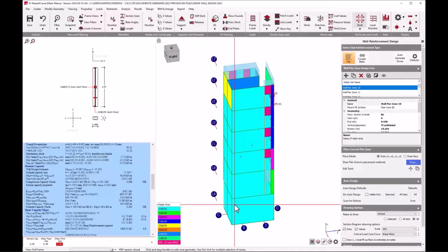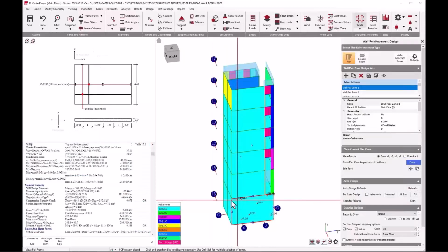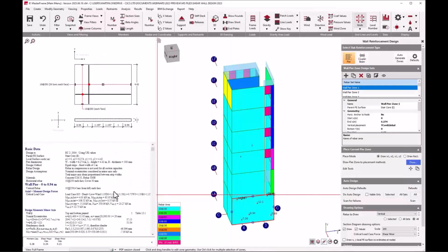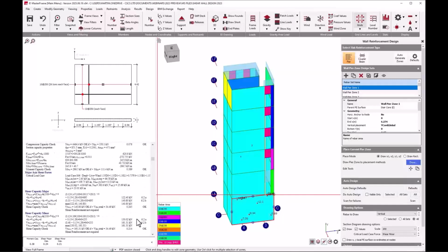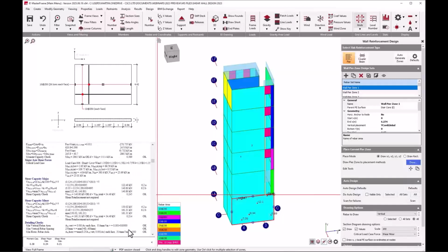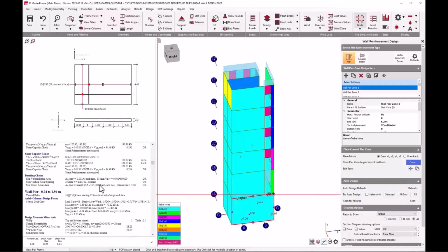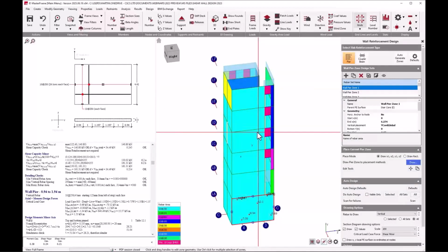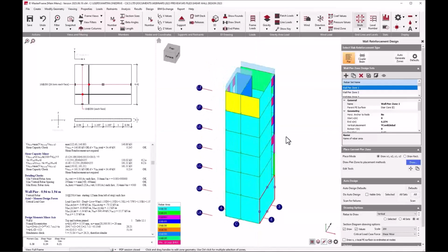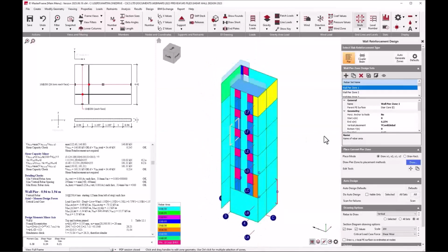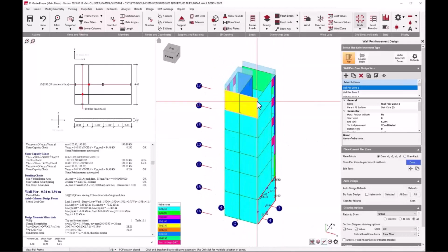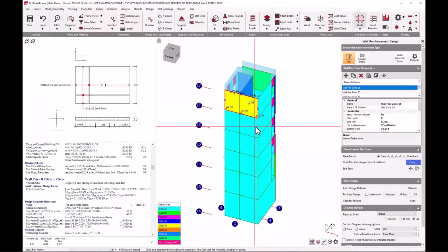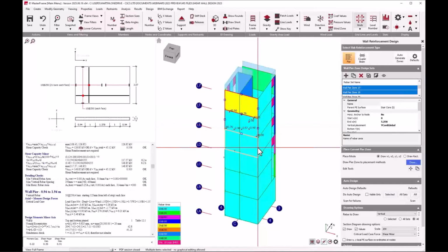I think we probably still have some problems in some of the zones simply because of some large design forces. So we can see we've now gone from 16s at 200s to 10s at 250s. Not much problem here in any of the major unity ratios, all well within capacity. We can see really it's the minimum reinforcement that's driving these 10s at 250s here in this instance. A few areas where we've got greater than the minimum, we've got 25s and 250s here.